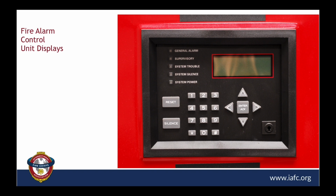which really brings us down to the next set of buttons that are on the left-hand side here. I'm going to drop all the way to the lower left where you see the silence button. On this particular system and panel, you come in, you see what's happening on the display, and you're able to hit the silence button and silence the notification in the building if you so request. Then once the problem is resolved, you hit the reset button up here to reset the system.